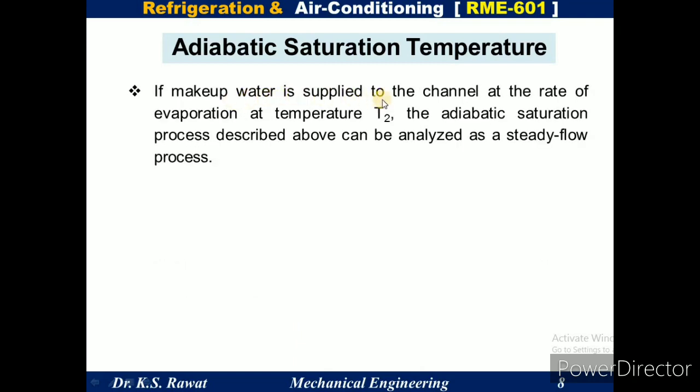If makeup water is supplied to the channel at the rate of evaporation at temperature T2, the adiabatic saturation process, which is described above, can be analyzed as a steady flow process. So we can analyze this process by considering the steady flow. So there is no accumulation of mass or energy. Apart from that, we have to remember that the makeup water supplied to the system is equal to the rate of evaporation. So the rate of evaporation of the water and the rate of feed water are the same.